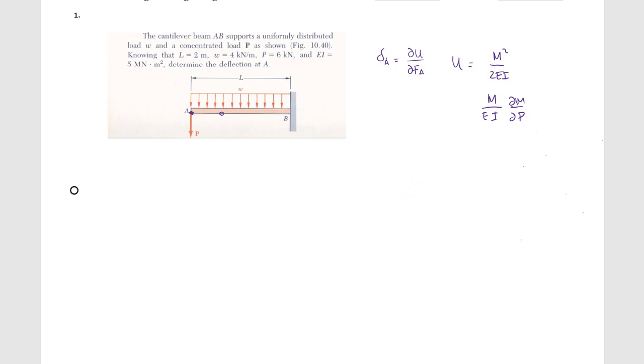So going back to this problem, I want to calculate that deflection at A, delta A or Y_A, which is the integral from 0 to L of M over EI dM/dP dx. Where if I do a cut here anywhere between A and B, I would see this load P, this distributed load W,